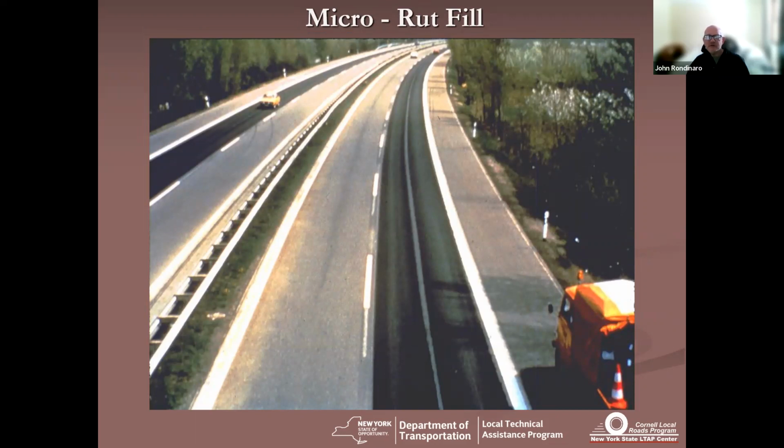Microsurfacing can be used for rut filling. Originally it was developed in Germany specifically to fill ruts. So in this case, on the right-hand side of the slide, you see two rut fill passes, and they attach a V-shaped rig to the outside within the spreader box, and that channels your microsurfacing material into the ruts.